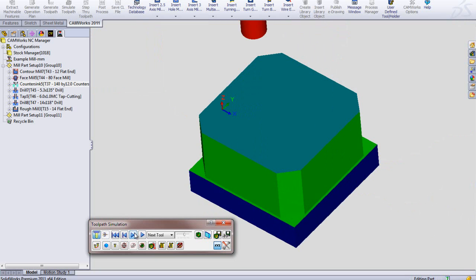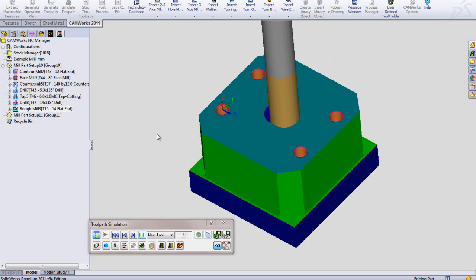Okay. And next we're going to get this countersink coming in here, making some start holes. And we're going to have a drill coming in. And finally our tap is going to come in here too, our M6. And then we're going to be drilling through here, and doing the center cutout here.